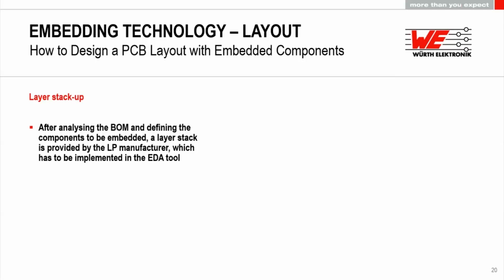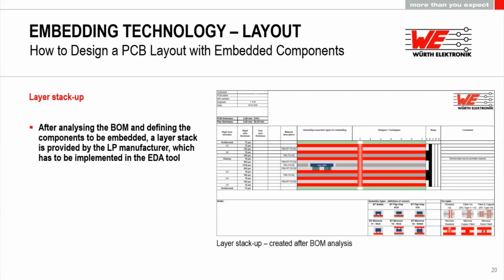And let's come to the stack up itself. During the project phase, when we were analyzing your bill of materials, the BOM, together with you, and defined the components which can be used for embedding, we provide you with a layer stack up. This layer stack up has to be implemented by you into your EDA tool. So far, we do not offer to directly send you the Altium-based, tool-specific stack up.